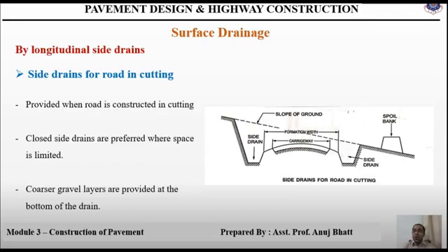Sometimes open and deep side drains cause accidents. So for such cases, closed drains are more preferable. In such cases, covered drains or drainage trenches properly filled with layers of coarse sand and gravel may be used. Coarser gravel layers are provided at the bottom of the drain.